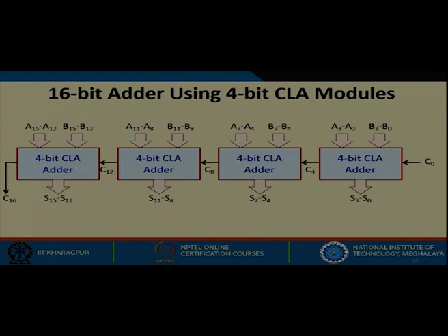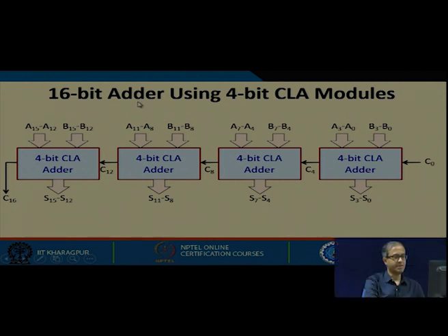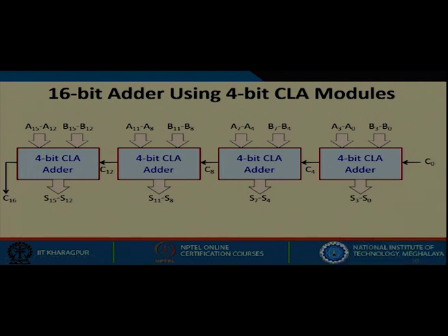But 4-bit is too small a number. Let us say we want to design a 16-bit adder. Well, having a single 16-bit carry look ahead adder will become impractical, as I have just said, because the expression for the carries as you go up to the higher stages will become exceedingly complex. The product terms will become larger, and the number of terms will also become very large, requiring very large OR gates.